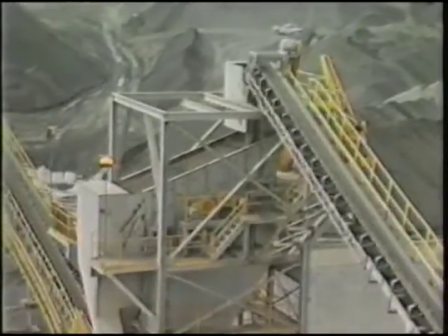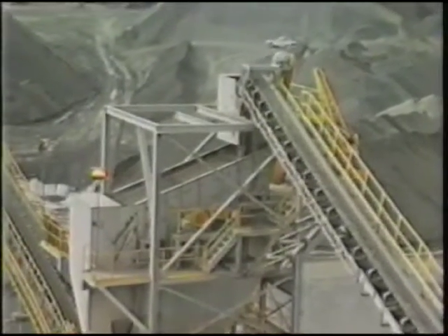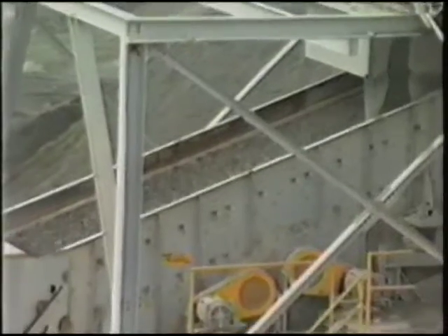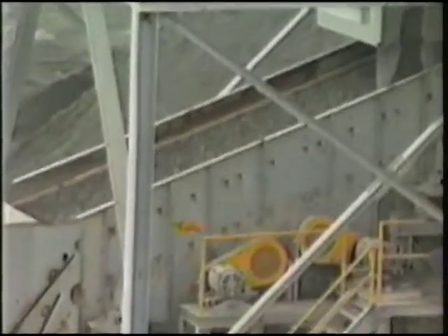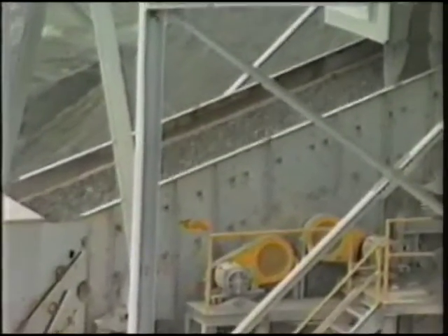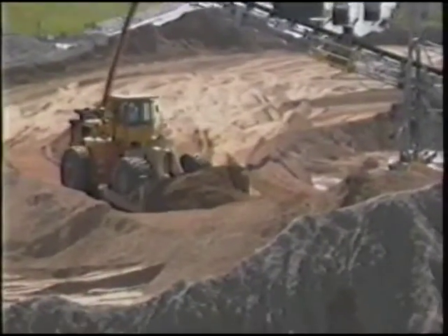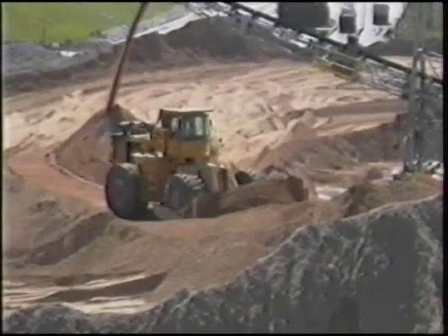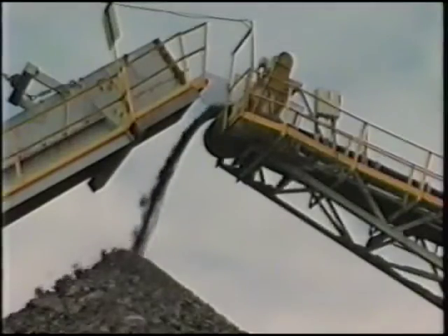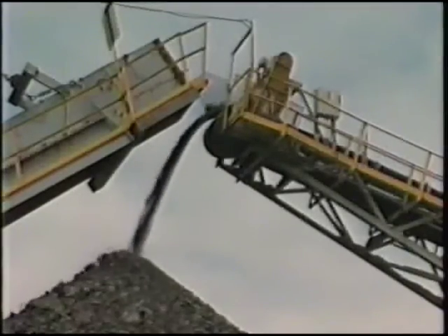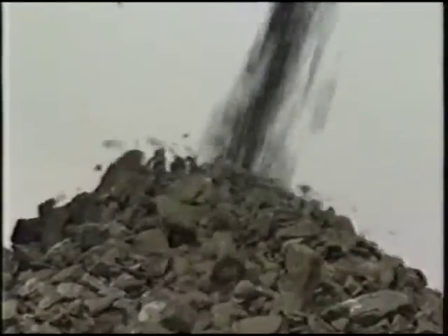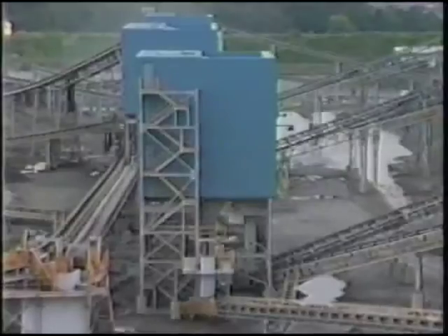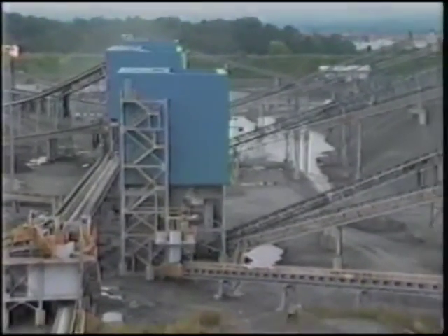Stone leaving the secondary crushing and screening stage may be conveyed to another sizing screen. The primary function of this screen is to remove everything typically passing a 1.5 inch opening. This material is crusher run and generally represents 30 to 50% of total production. Material larger than 1.5 inches is called surge stone. It is either conveyed to a surge pile or is fed directly to the tertiary circuit.